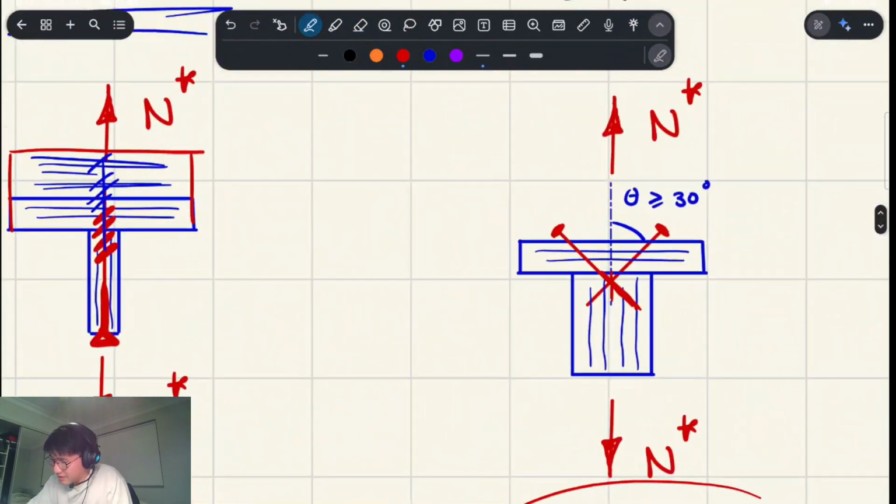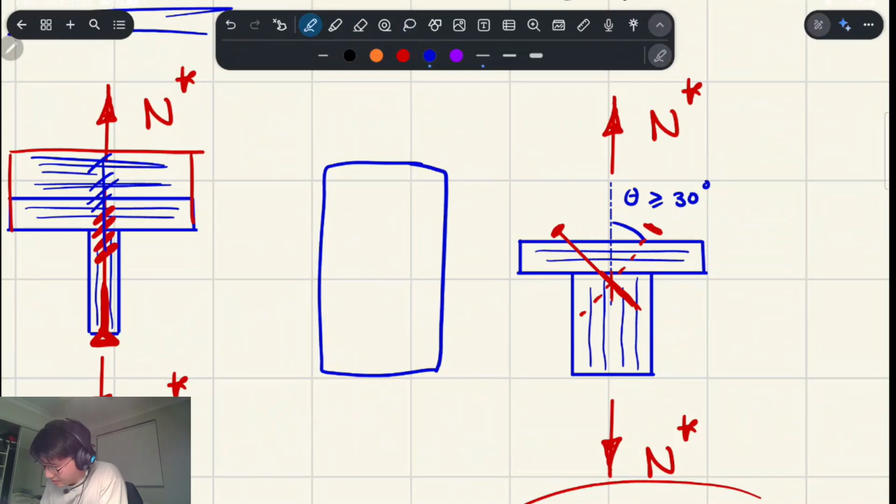And how those would typically go is I've kind of drawn them like they're in the same plane, but one would technically be behind another, and you would stagger them, right? So the dashed line there is representing that it's behind the one in the foreground. So this one's in the foreground, and this one's in the background, and you would stagger it like that. So maybe in a top-down view, you would have one nail going like that, one nail going like that, one nail going like that, one nail going like that, etc. And that's going into the material, right? Like that.